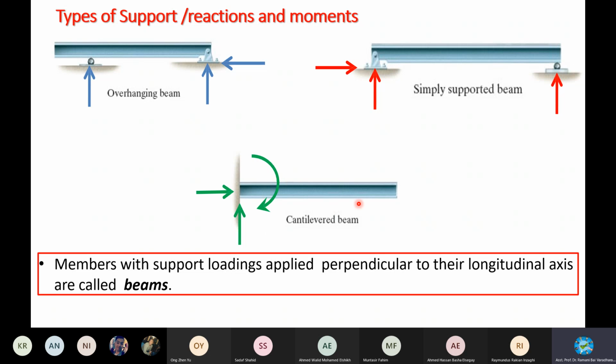And this is the cantilever beam. A cantilever beam is one that is completely fixed, maybe driven into the wall or welded, riveted with brackets and so on, firmly into the wall, into the structure, into the frame. It is totally restrained. Moment is totally arrested for this member, and the other end is free. Then it is called a cantilever. This cannot be called a cantilever because this end is just pinned, right? You may think, well, here also we have a free end, so why not a cantilever? No, it cannot. It's an overhanging beam because it's a pin. If it is fixed here, then it can be treated as a cantilever. I repeat, one end fixed and the other end free means cantilever.